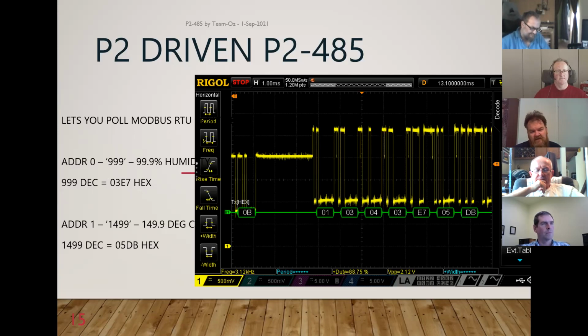But frankly, it's easier just to use the ability to spy on a pin from a couple of pins away and leave that spy in a permanent receiving mode. That way you've always got the data received. In a nice final object, it'd be nice to have the bus turnaround. As you can see, there's about 3 milliseconds between the P2 ending transmission and when you've got to pick up the incoming received data. And this is a fairly slow 9600 baud application.